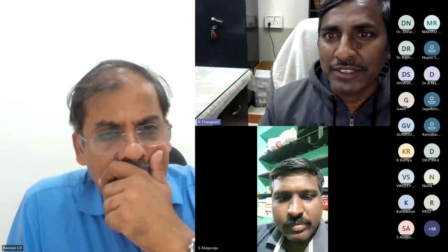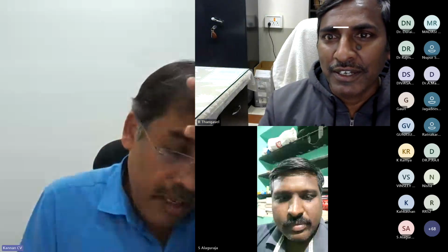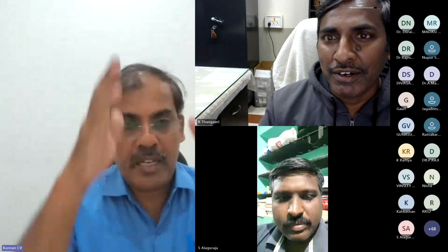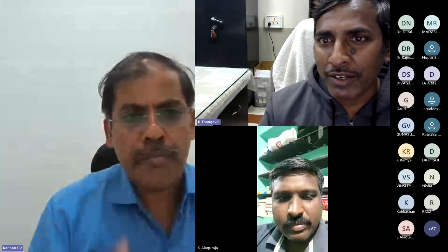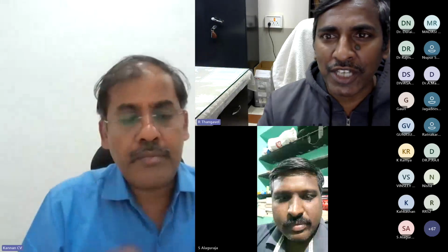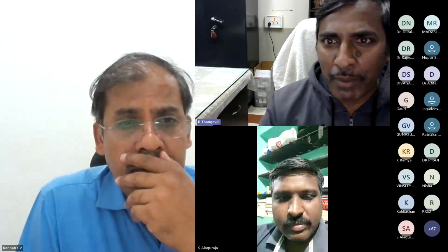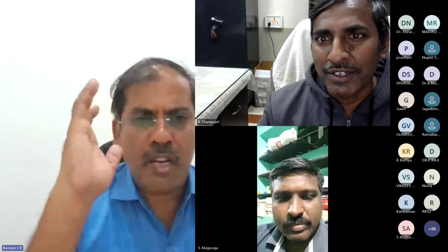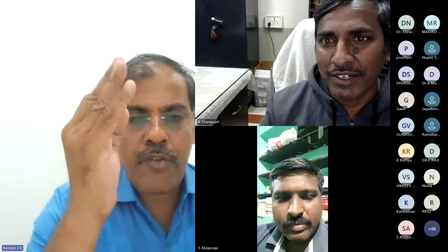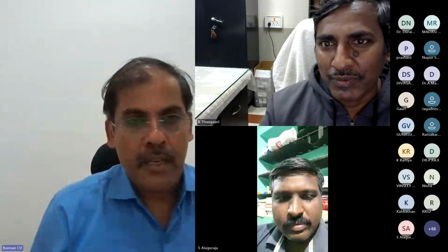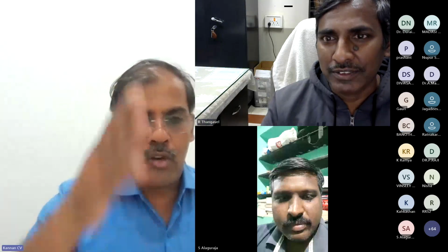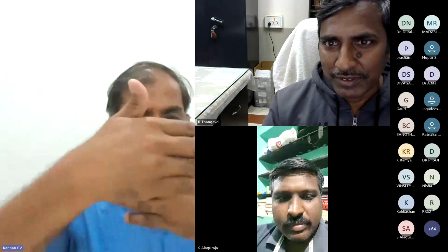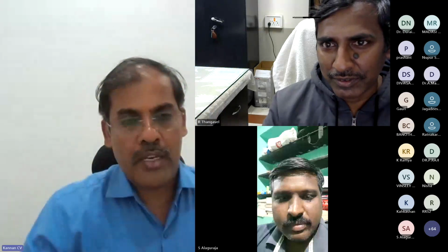Non-contact method. You can also measure non-contact, or since it's a crystal, you can contact. You can contact also. It's not going to impact anything. Anyway, if you contact, then the crystal will be damaged a little, right? No, because it's a solid piece, a 300 mm solid piece. By touching it, anyway you have to cut the piece, because you are measuring only the round crystal. After that, you have to slice all four sides, converting the round crystal into a square crystal.